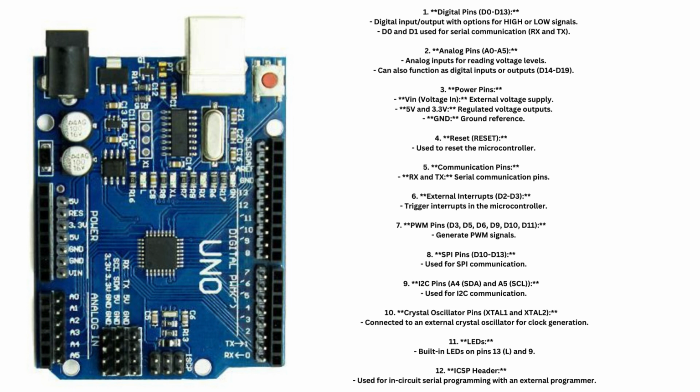10. Crystal oscillator pins, XTAL1 and XTAL2, connected to an external crystal oscillator for clock generation. 11. LEDs, built-in LEDs on pins 13, L, and 9. 12. ICSP header, used for in-circuit serial programming with an external programmer.